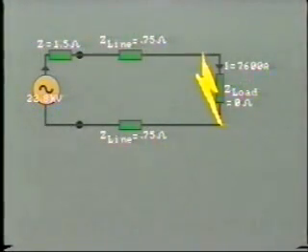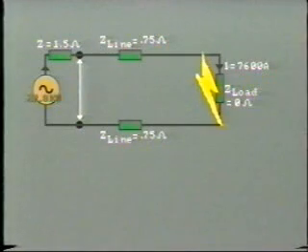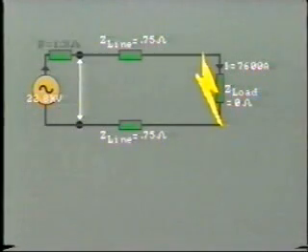And what about the voltage throughout the system? Well, as we consider the short circuit to contain no impedance at all, the voltage across the load will now be 0. And at this point, at the beginning of the line, voltage will be 22.8 kV, the internal generator voltage, minus the voltage drop across the generator impedance.